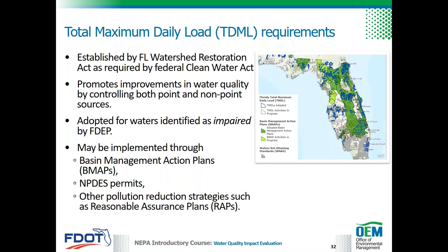Florida has also established the Total Maximum Daily Load, or TMDL program, as required by the Federal Clean Water Act, to improve water quality from point sources and non-point sources for waters identified as impaired by FDEP. TMDLs may be implemented through BMAPs, NPDES permits, or other strategies. FDEP implements a reasonable assurance program to restore water bodies to meet their designated uses and alleviate the need to establish TMDLs. The list of approved RAPs is found on FDEP's website and is updated regularly.